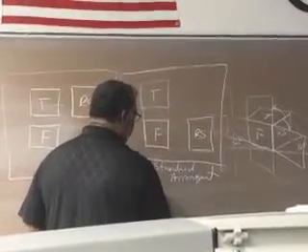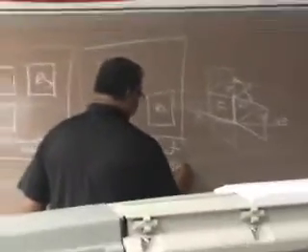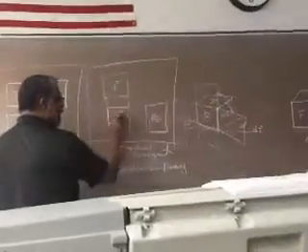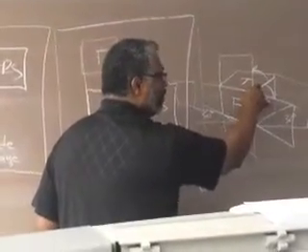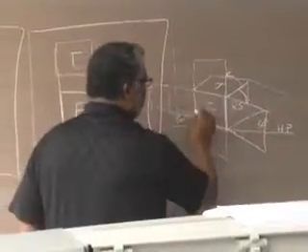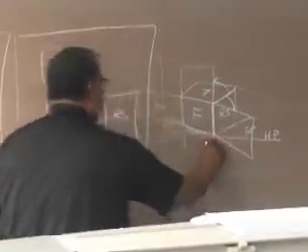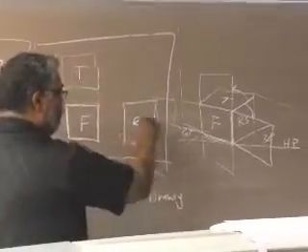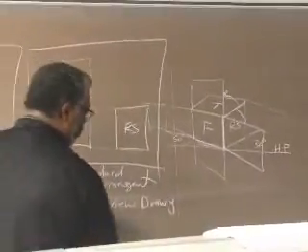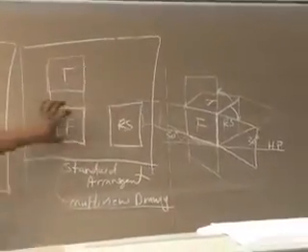This is referred to as multi-view projection or multi-view drawing. To get to here, you got to do orthographic projection. Orthographic projection is a term used to extract your views, top, front, right side, and so forth. But when you place them on a sheet, add dimensions and stuff, and maintain that arrangement, it's called multi-view drawing. So we're dealing with orthographic views as part of a multi-view drawing. So you use the terminology multi-view here.